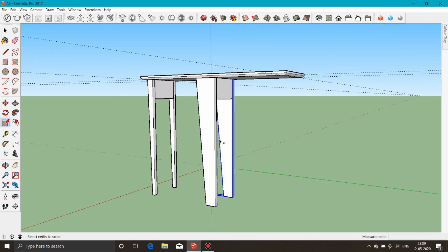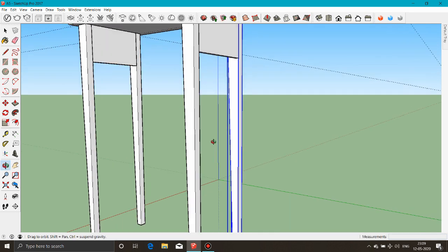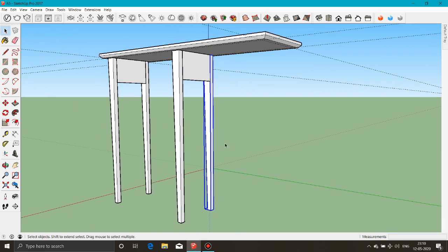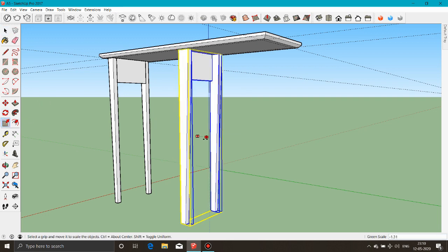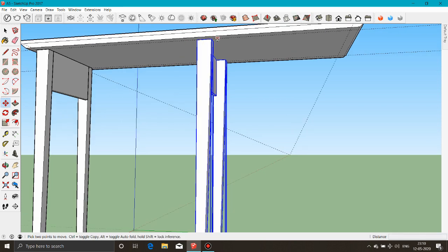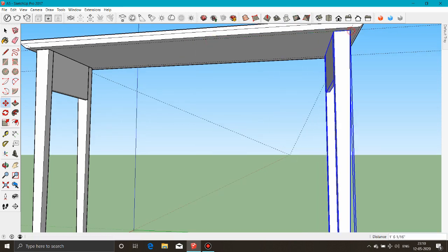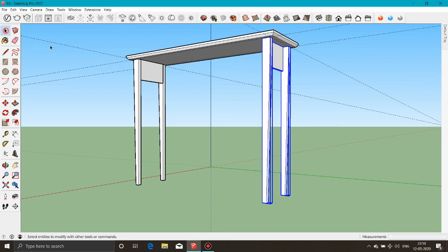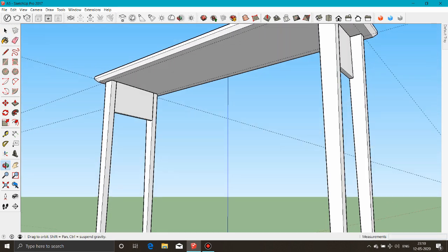Make sure all 3 parts are selected and choose the Scale tool. Scale works by clicking to move the control grips. Any of the corner grips will scale everything uniformly. However, choosing a center grip will scale it only along that axis. Watch how this works by trying several of the grips. Pay special attention to the center grips, which scale along the red, green, and blue directions. If you squash the geometry through itself, you can mirror the object in that direction.